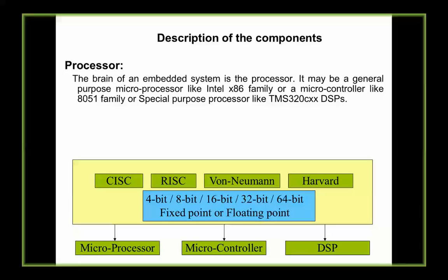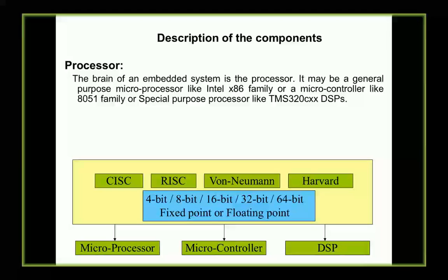There is something important over here: microcontrollers versus microprocessors. A lot of people prefer microprocessors because they want more flexibility and they're willing to perform some manual interfacing for other components. So if you are at a deep-dive level and you have a good engineering team on the hardware side, and you want more flexibility where you can pick and choose certain components and then connect them based on your new design and layout, then a microprocessor could be a good choice.